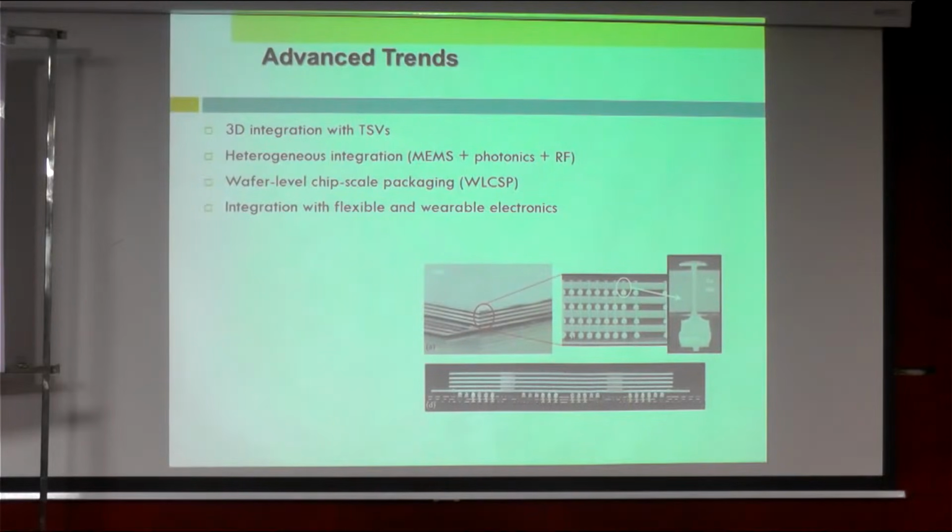TSV is considered one of the advances in MEMS packaging and MEMS design. So you can see here, you can stack a lot of chips and also devices. If you can connect, let's say this is just 200 to 300 micrometer, so you just stack it up, rather than connecting at the side or with some other means of connection, just stacking with a few micron thickness between the solder balls here.